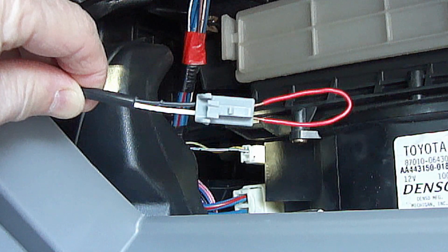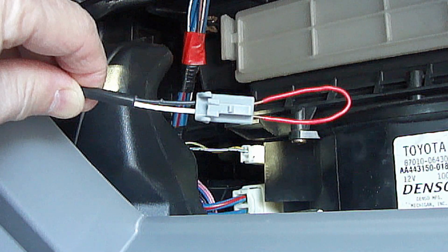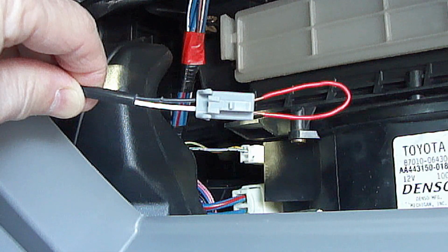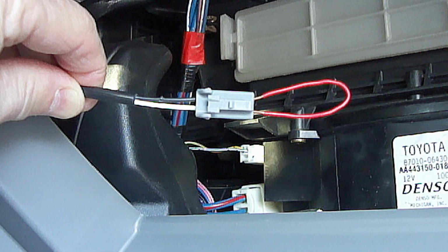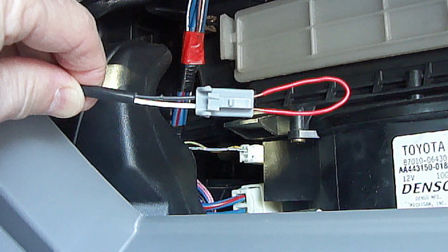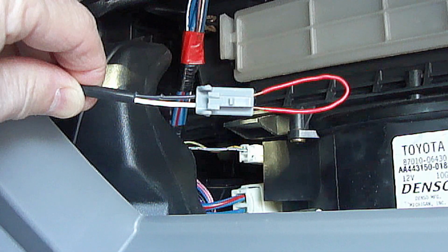If the clutch starts turning after bypassing the sensor connection like you see here, then this indicates that the sensor is bad and needs to be replaced. Be advised that if you do not replace the sensor and leave it bypassed, the compressor will run continuously and cause premature wear. The evaporator may also ice up and not allow the cabin to cool properly.